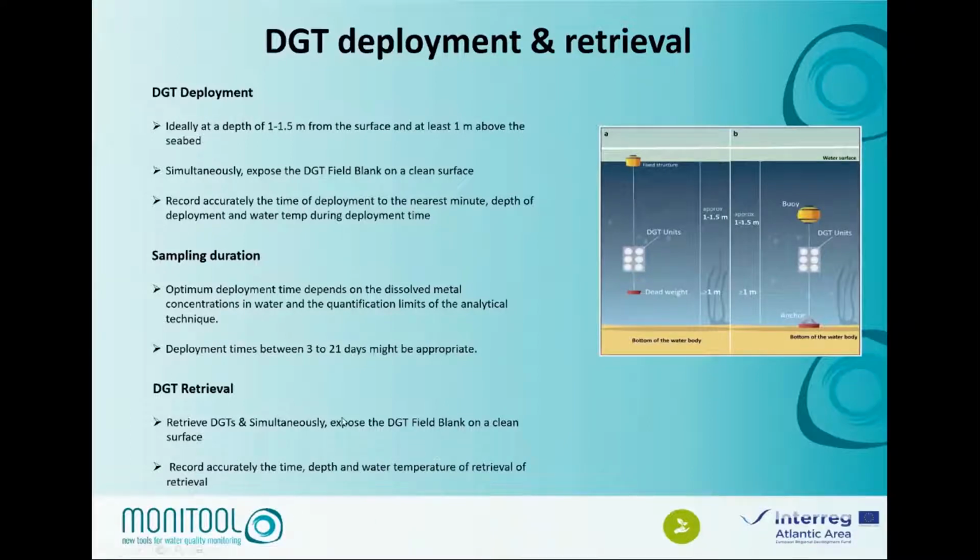When it comes to retrieval time, we proceed as we did for deployment, in that we expose our field blank DGT onto a clean surface when we're retrieving the DGT. Once everything is out of the water, we put those field blanks back into the plastic bags and keep everything refrigerated in the cooler box.